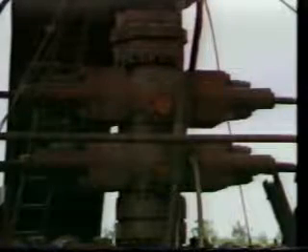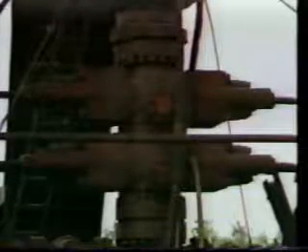Blowout preventers are a series of powerful sealing elements designed to close off the annular space between the pipe and hole, where the mud is normally returning to the surface. The BOP stack consists of an annular preventer, a donut-like rubber ring which may be hydraulically squeezed to conform tightly to the drill pipe in the hole, pipe rams, which contain rubber-lined steel jaws designed to grip the drill pipe, blind rams designed to close off the hole after the pipe has been removed, or shear rams designed to actually crimp the pipe in two, sealing the hole in an emergency.